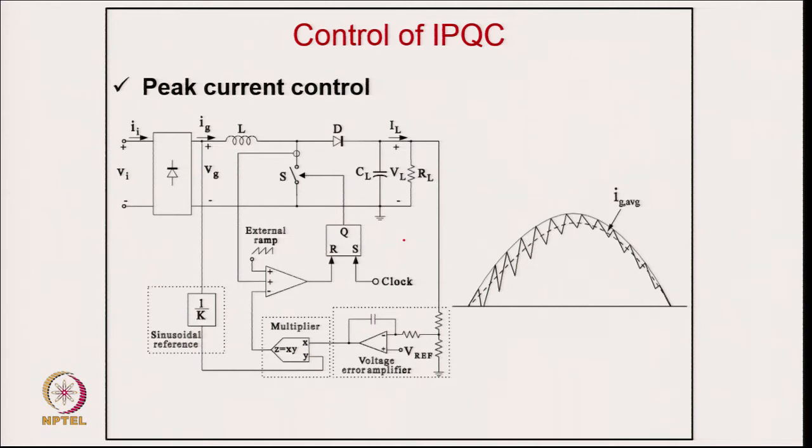Apart from that, you could get a good quality current in the input supply. Output voltage still can be regulated, even if input voltage varies over a wide range. So, you might have a voltage power quality problem, but still the loads connected at the output of the converter are not supposed to be affected by such power quality problems on the supply side. Of course, for this boost converter you will find a lot of literature, and it is now appearing in most books on power electronics, because they are very extensively used.